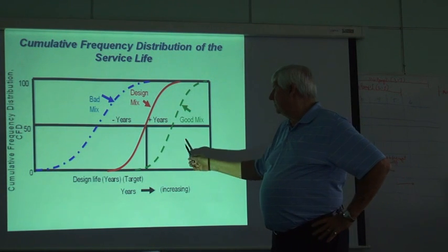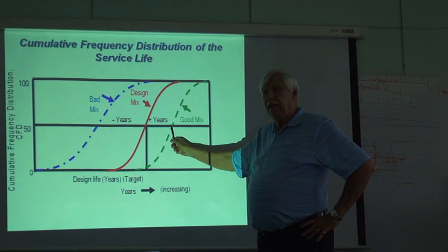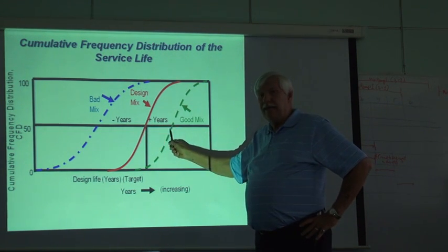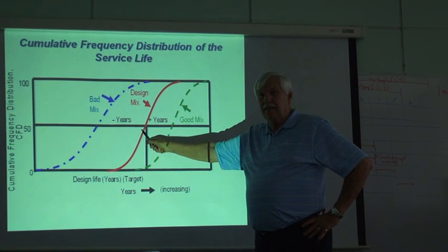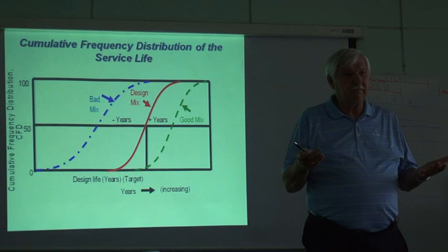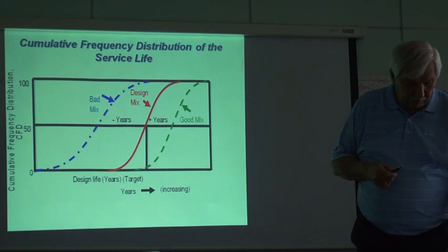what he's doing is in reality decreasing the life of the road. So that when I subtract this from this, again, what I place minus what I thought I had, the as-built minus my design, if this number is positive, I'm in good shape. If it's negative, the contractor's in bad shape. Okay, so that's the simple concept of what we're doing.